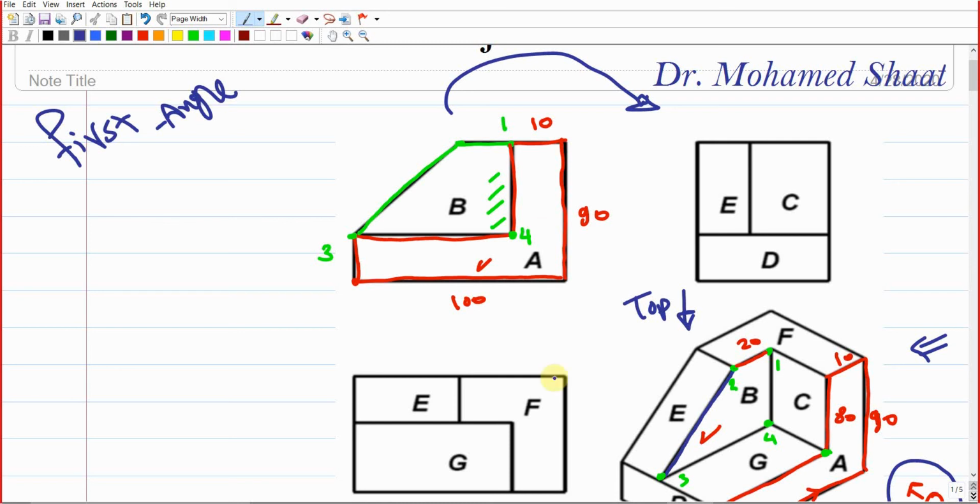Make sense? So to create this side view, there are some essential things that you should understand, as we discussed before: the maximum height or any feature, whatever it is, in the front view should be seen in the side view. What does it mean? It means that if you look at the front view we already drew, and assume that this drawing is not there yet, and you look at it from this angle, you have to see the side view. So what are the lines or edges that you're gonna see?